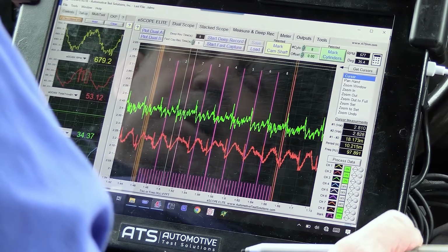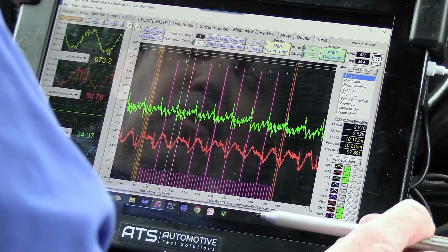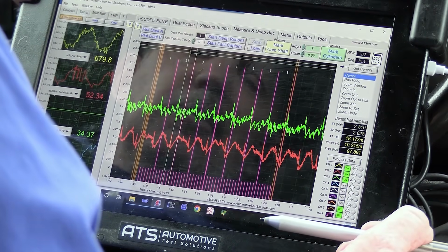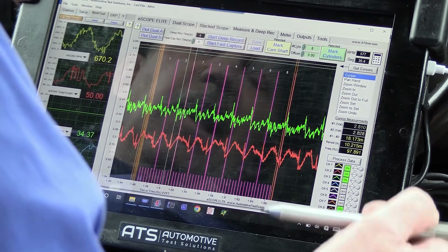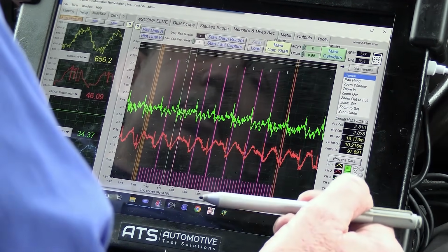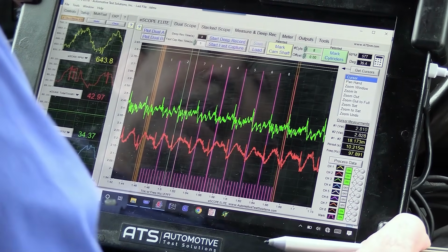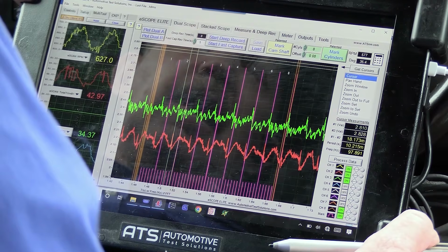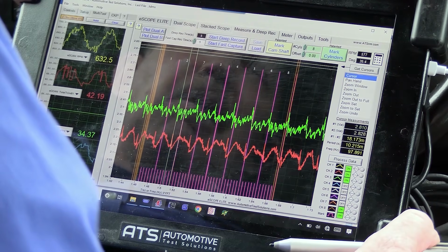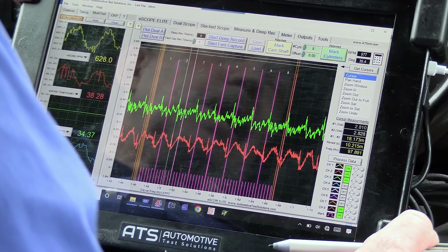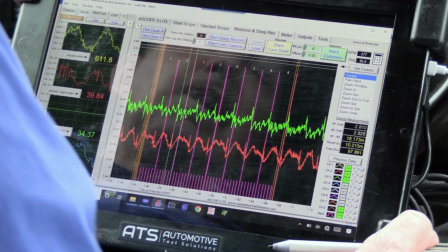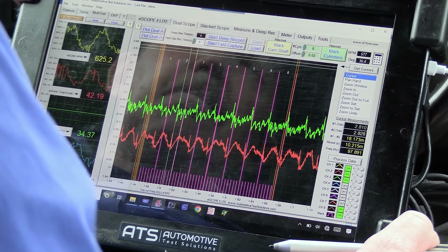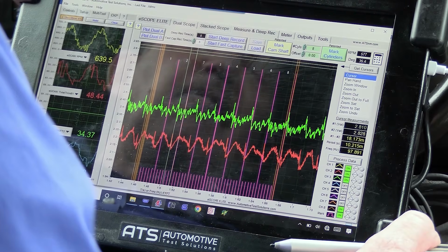Wow, that's incredible, guys. This is really, really cool. Look at that. The jack shaft chain is loose. That's what's wrong with this car. And that answers a whole other question that I've been looking to figure out in the data. When we first worked on this car, we saw that I'd get in it and out of it, and that's when I'd get my problem. And I thought it was because I had the fuel sloshing, and when I sloshed the fuel, it was cavitating in the pump.